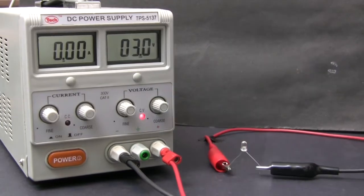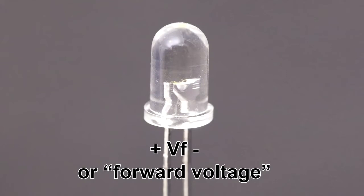If you get the polarity wrong in your circuit, don't worry. For low voltage projects, the backwards LED blocks current from flowing, and it just doesn't turn on. Okay, now let's talk about the forward voltage of an LED. All LEDs need a certain voltage across them in the right direction before any current can flow and they start emitting light. This particular white LED I'm using has a forward voltage of 3 volts, so we need around 3 volts before it can do anything interesting.